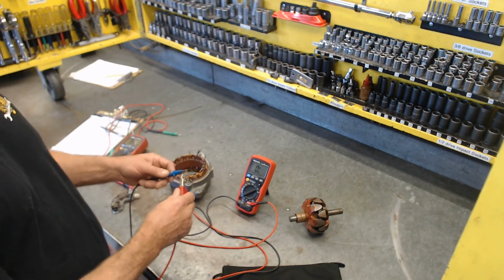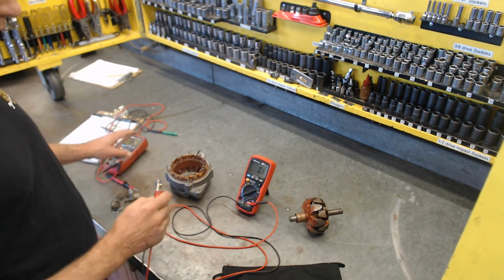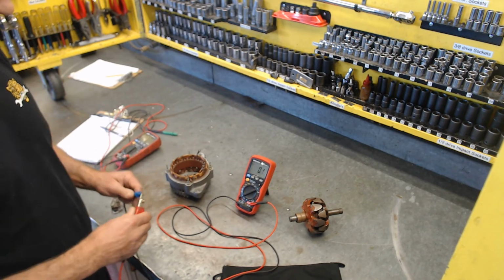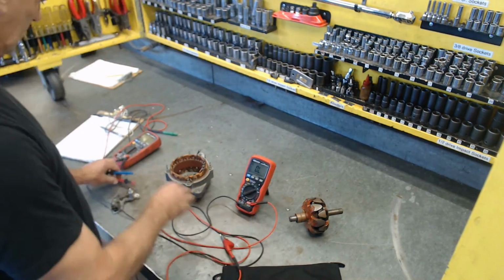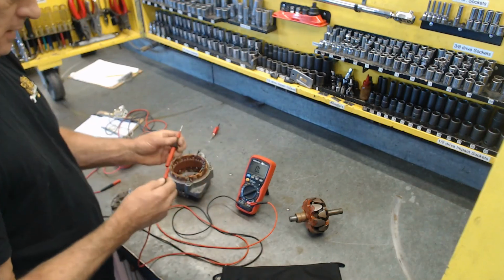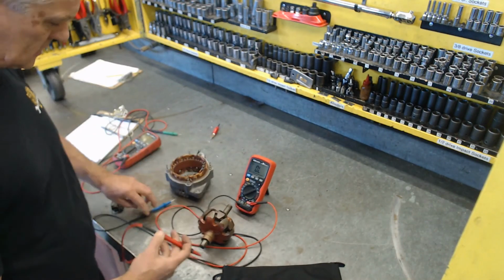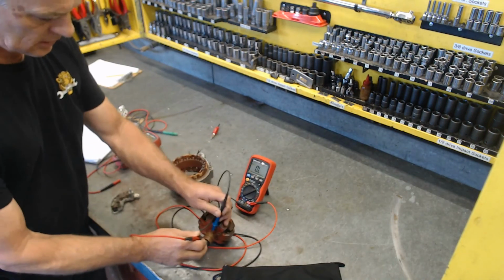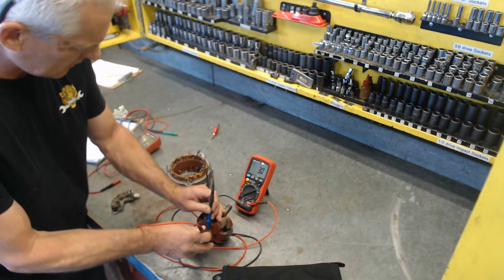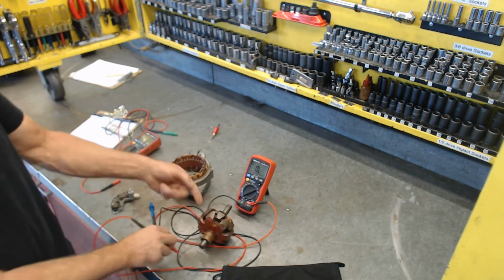You can see it's reading OL. When I touch it together, it goes to like 1/10 of an ohm. So I'm assuming on this other meter that the battery may be going bad. So I'm going to go ahead and swap this lead out here, and I'm going to touch the rotor across the slip rings like this, slip ring to slip ring, and I am reading about 3.1 ohms, so about 3 ohms of resistance in that coil, and